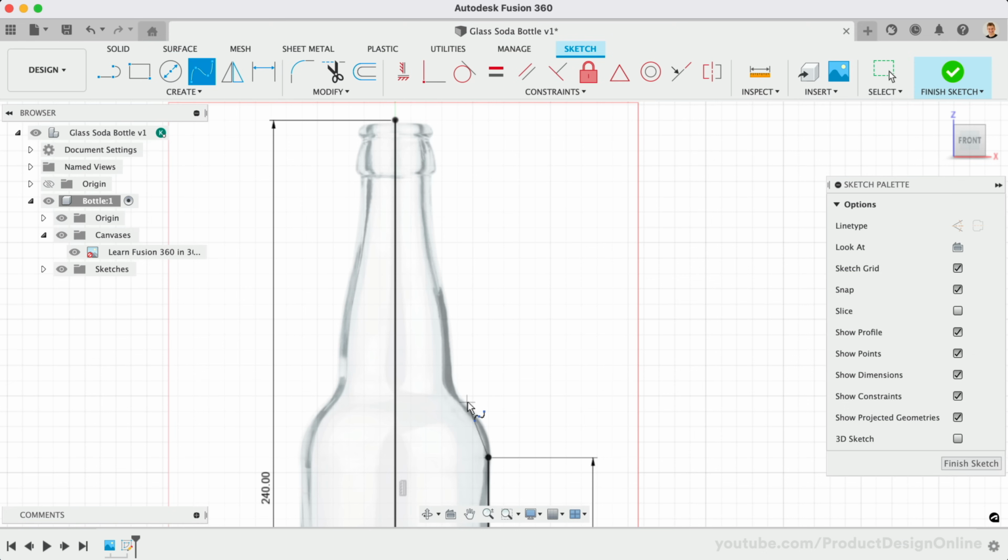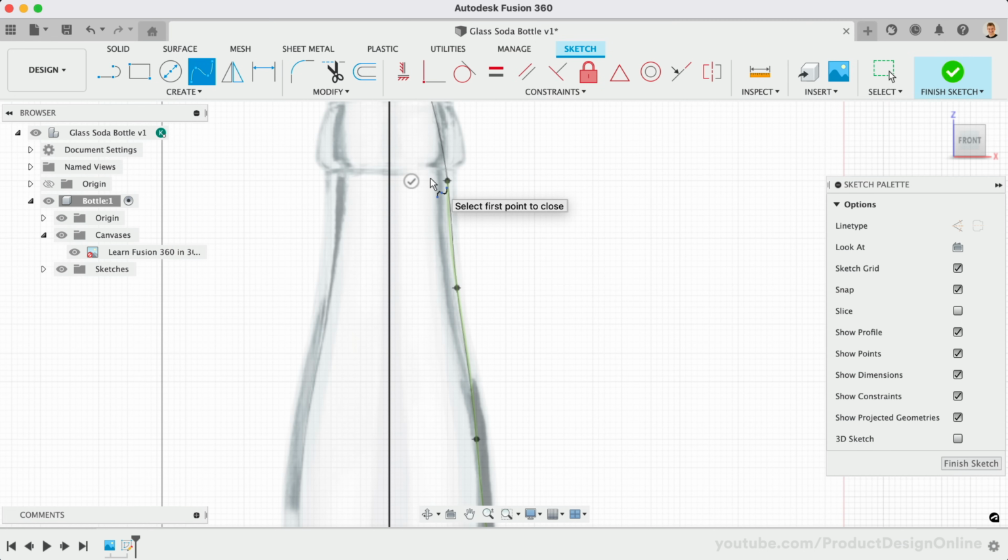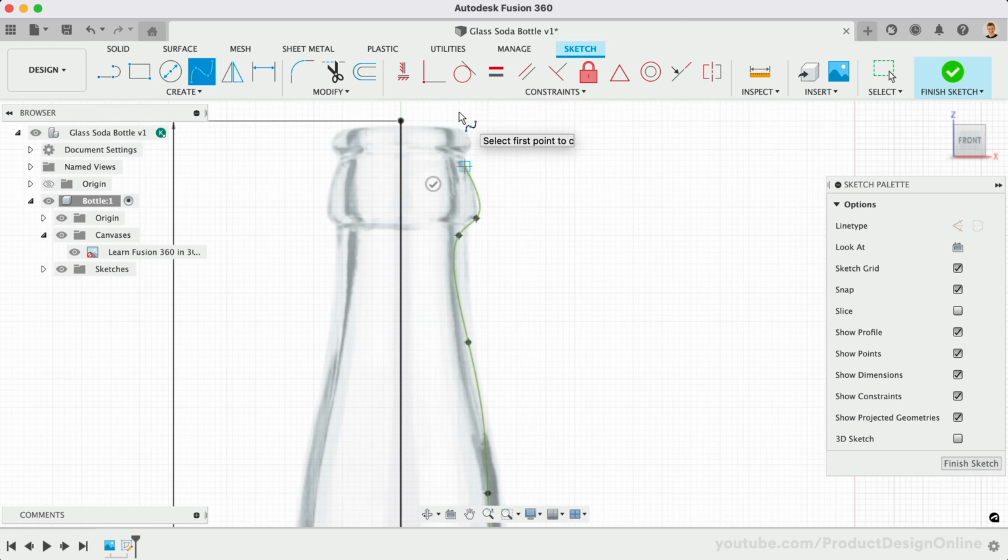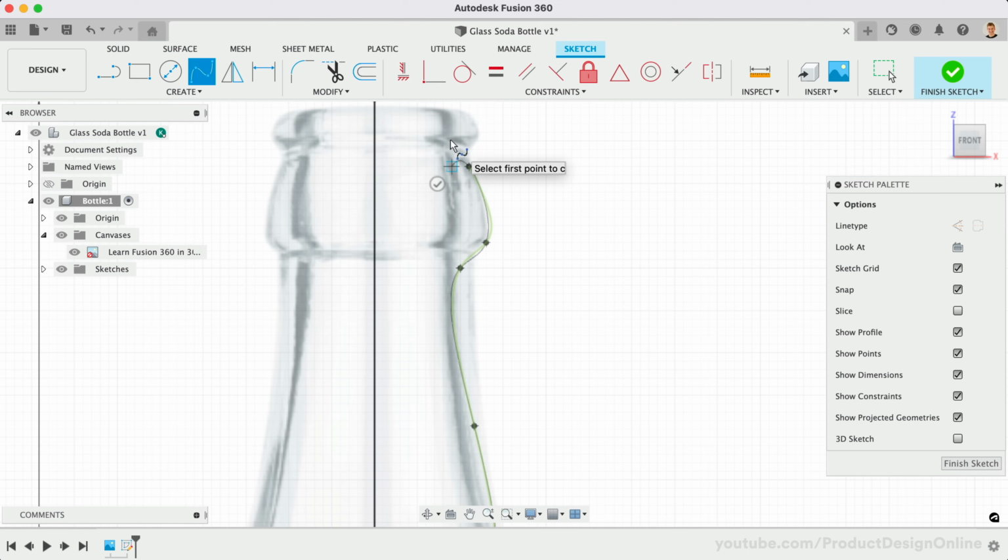It's considered a best practice to use the least amount of fit points as possible. This will help you maintain smooth and realistic geometry. Take your time to select each point where the curvature changes, keeping the points to a minimum. Keep in mind this does not have to be perfect, as we can adjust the points after.